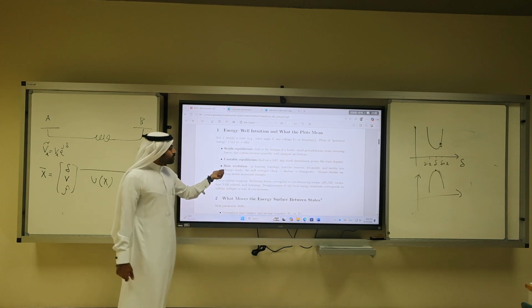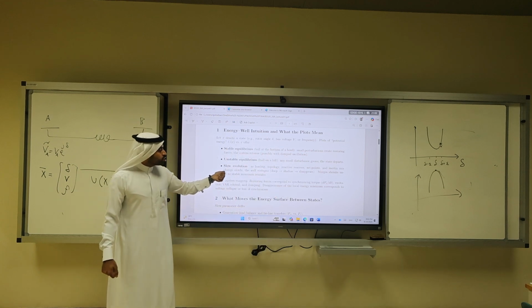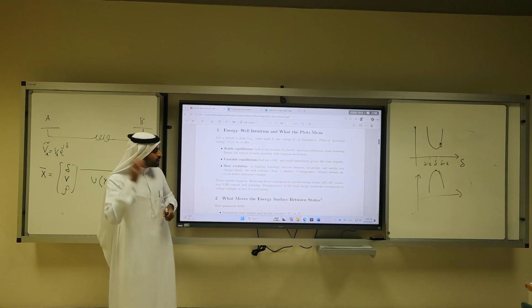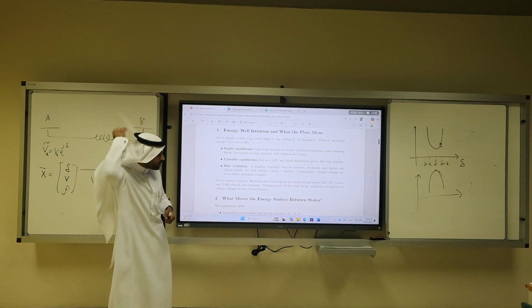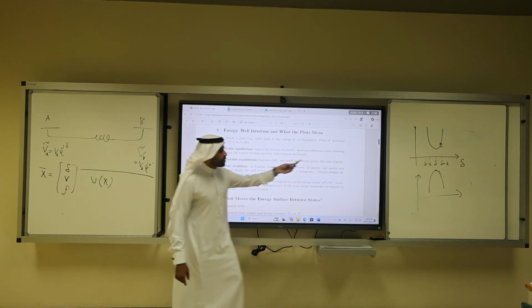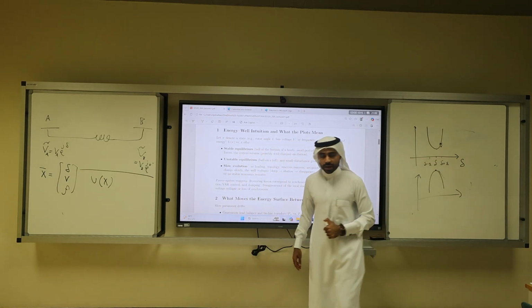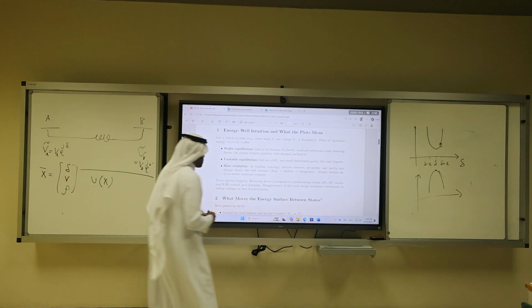Or we change the inertia mix slowly by adding renewable energy, where there are inertia-less PV panels, they are bad when it comes to stability. They somehow mess around with the frequency. This will reshape these stability curves. Okay? It will reshape.